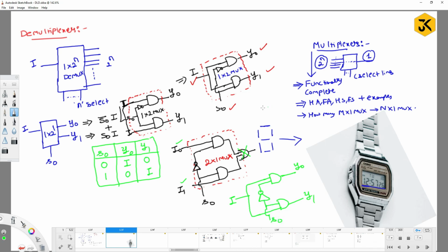If you observe, now these two are completely the same. Means how do we get a demultiplexer with the help of a multiplexer? You can just simply remove the OR gate and combine all the inputs into one input, right? These are the 2 points you have to make sure to understand to convert the multiplexer into a demultiplexer.